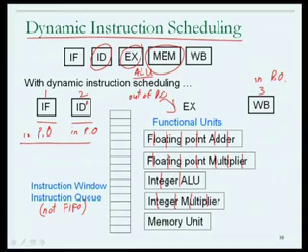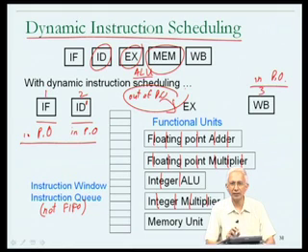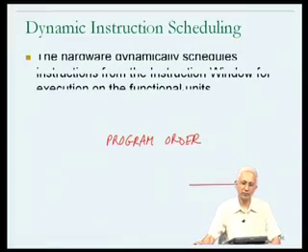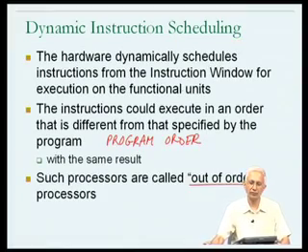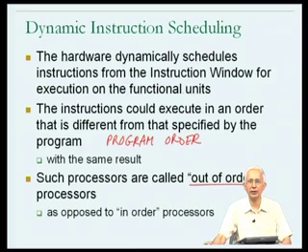And this is a common characteristic of many of the aggressively pipelined processors today. They are in order, in program order in their early stages. They finally finish instructions in program order. It is only in the intermediate stages that, in order to eliminate data hazards or to improve performance, they handle instructions in a carefully checked different order. Hence the term that you may see in some of the literature or in sales literature that you read about an out of order processor. So much for instruction scheduling.